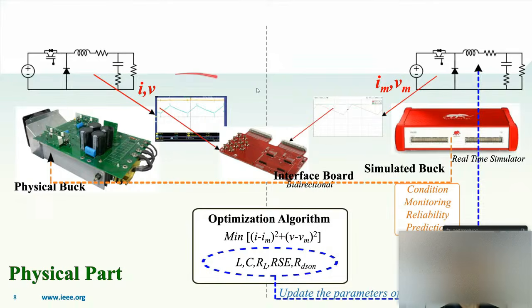But again, with a more realistic model, using now other algorithms like a probabilistic algorithm to detect some failures in these capacitors, we've identified that these spikes here are stressing the capacitors too much. Let's try to change the parameters of the controllers in order to soften this and maybe prolong its life cycle and other things. That's the idea of the digital twin technology, keeping the parameters changing all the time.